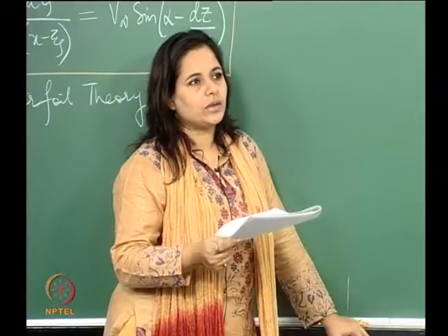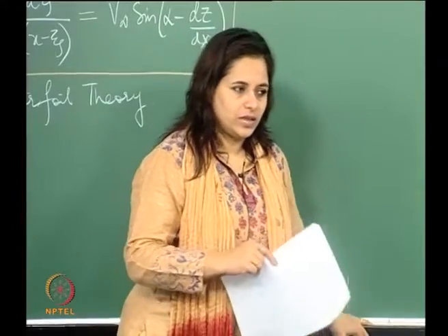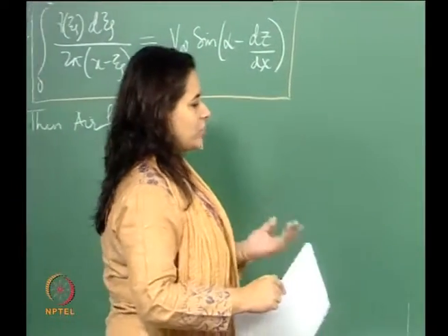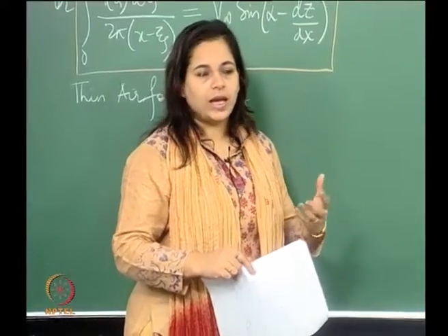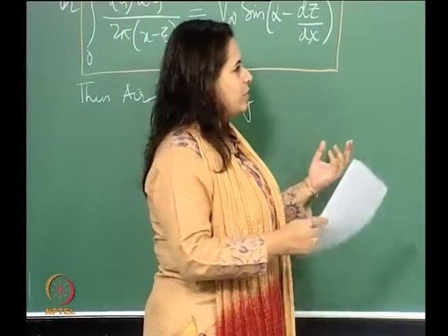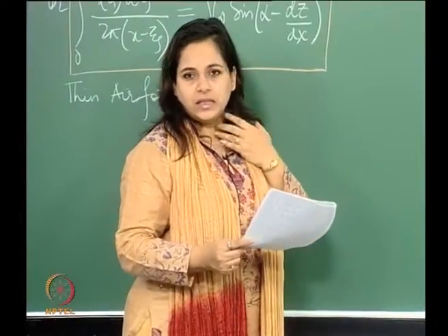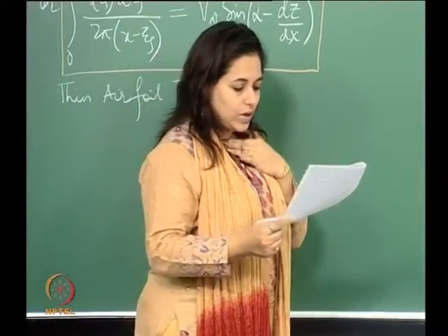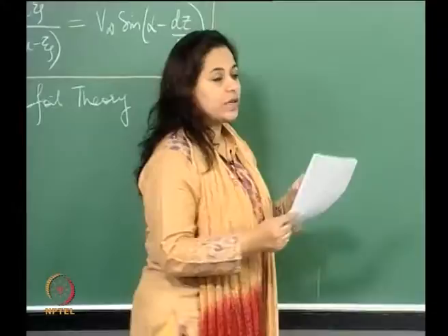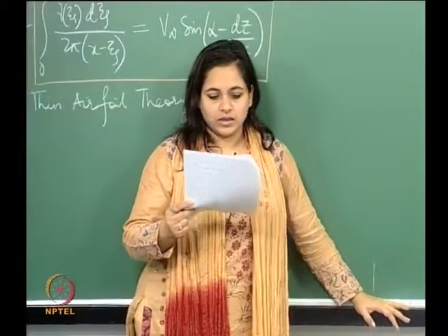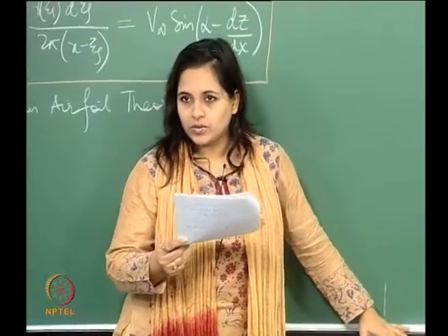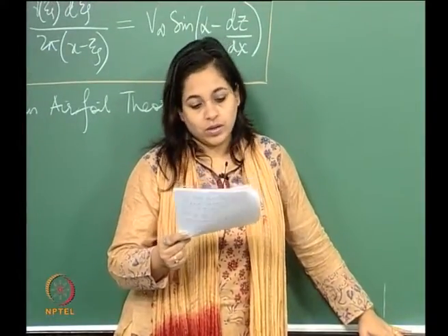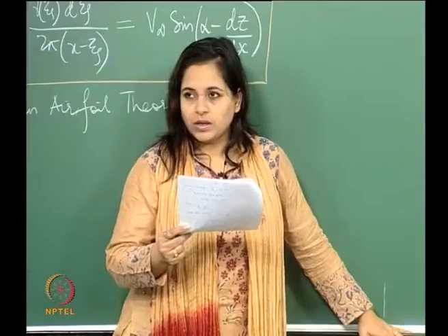So by now you should be understanding that when you use a linearized theory and add a correction to it, then we should get an expression for CL and CD in the supersonic stream. Because we're talking about compressible flow when you're saying supersonic free stream, whereas the linearized theory we used would not be compressible.